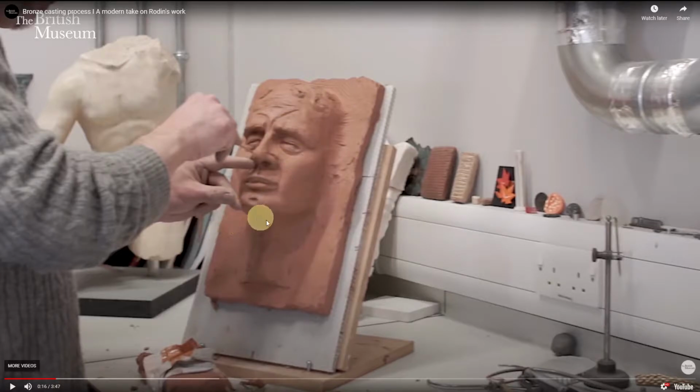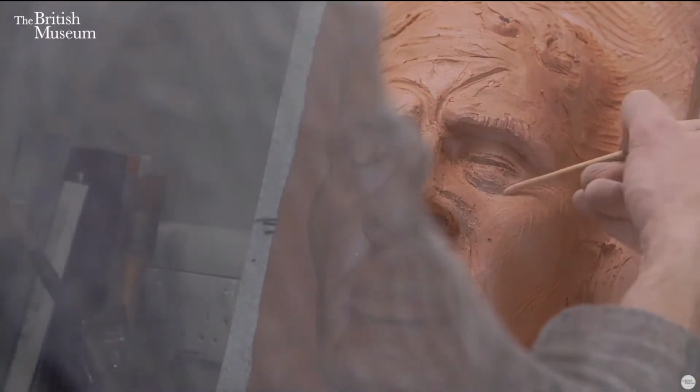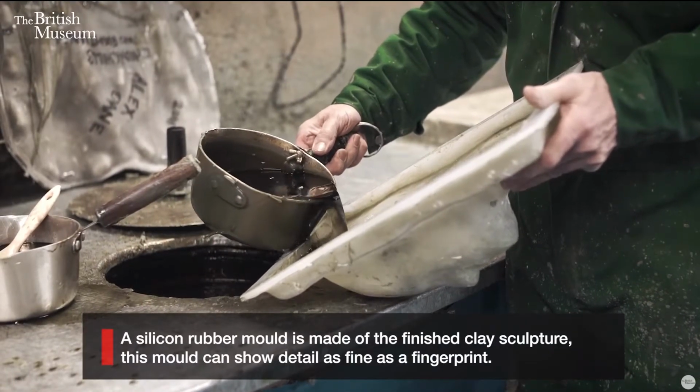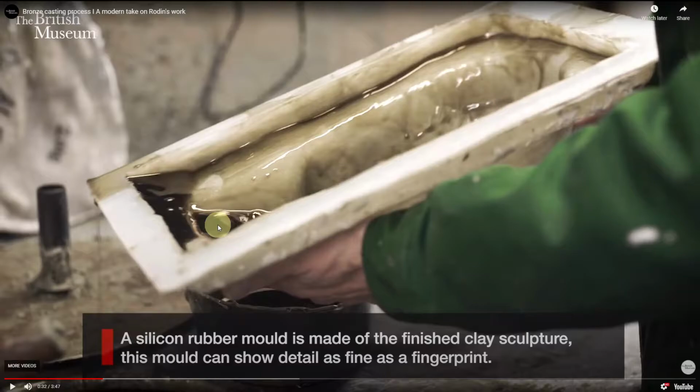You see he's modeling using the clay. And he used the silicone rubber to create the mold from that clay face that he made, and he's gonna pour wax in it so that he can create a mold around it. I think he's using silica casting, and then you can melt out the wax, and then he can pour the bronze in.